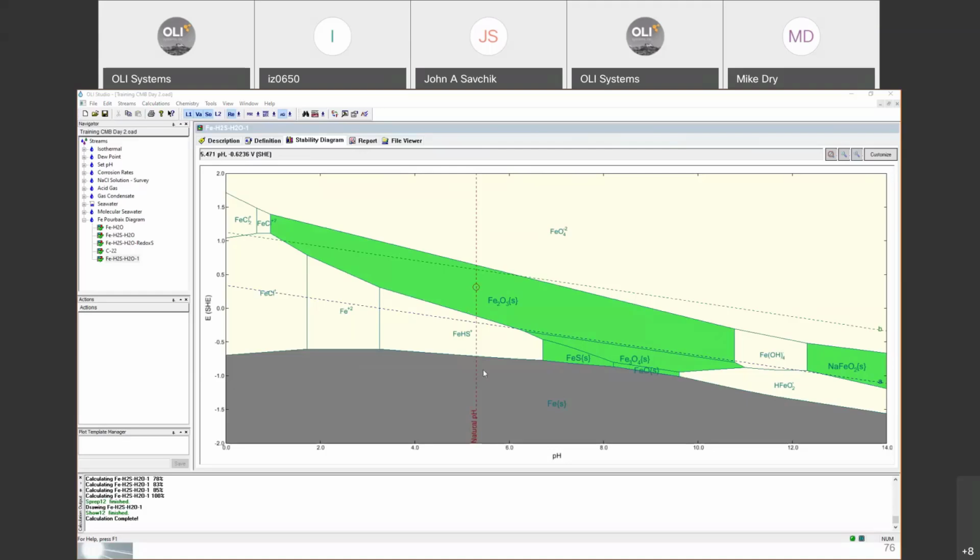Okay, let's say you are at this pH and you happen to be in the corrosion region. You can always add a base to increase your pH and make sure that you're here. Or you can make sure to increase the potential. That's what happens when you're doing cathodic protection, for example. You want to be in the green region. So sometimes you impress or add some current to the system to make sure that you reach the potential at which you will have that protection. In this case, you will need an oxidizing agent to increase the potential, like if you were in this region and you want to go up, you will need to add an oxidizing agent to locate the material in the green region.